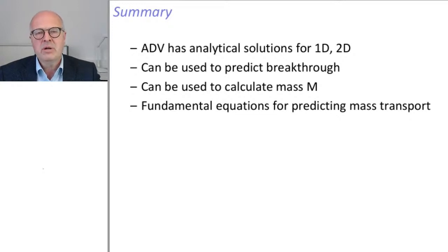The outlook for tomorrow is I have explained how we select the tracer, and I have explained how we try to predict the tracer concentration, how we calculate the tracer concentration. These are two key elements. Now, the advection dispersion equation also tells us when the tracer comes, so we can also plan our sampling strategy accordingly. I already mentioned that we should or could use up to 200 bottles per experiment.